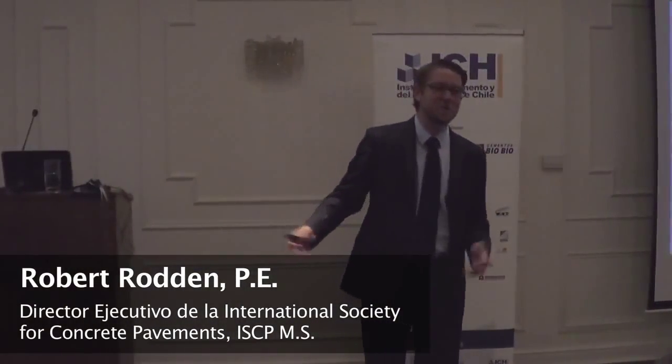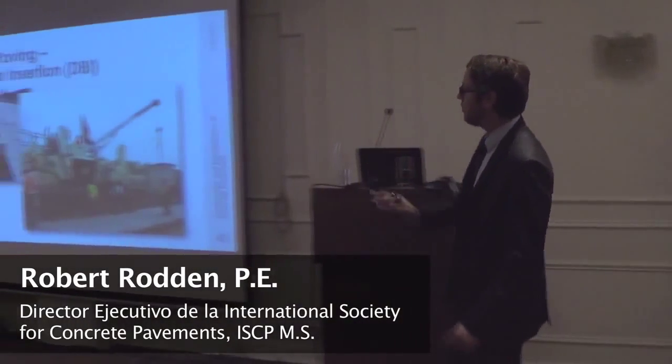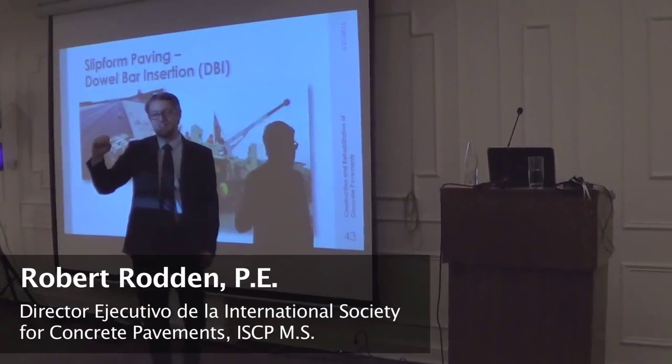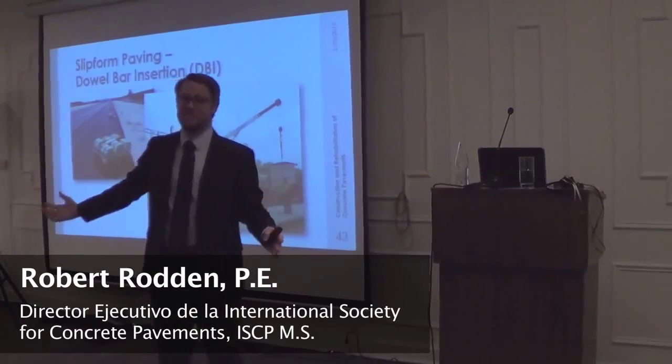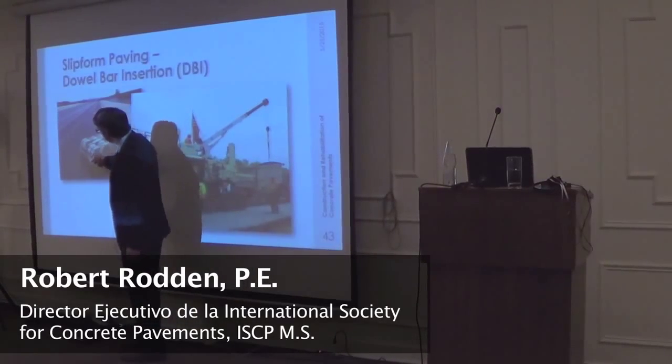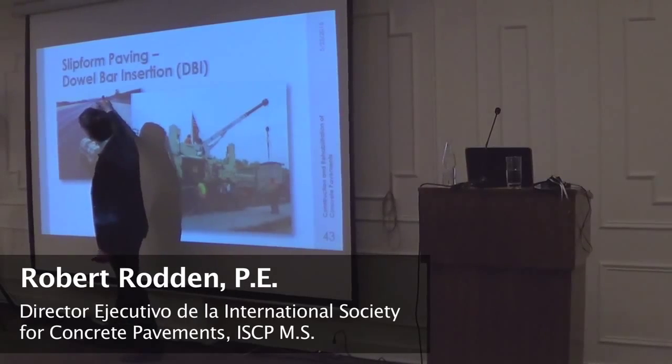So I understand dowel bars aren't too common, but you might find this a novel idea if nothing else. Because of the limitations of delivery and the challenges with placing the steel ahead of time, it's also cost-driven. It's much easier to transport this pallet of round dowels stacked like that than dowels in big baskets. So we'll have dowels delivered in bundles. Those get dropped at a regular frequency.